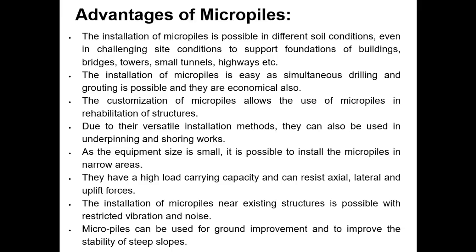The customization of micropiles allows their use in rehabilitation of structures. Due to their versatile installation methods, they can also be used in underpinning and shoring works. As the equipment size is small, it is possible to install the micropiles in narrow areas. They have a high load carrying capacity and can resist axial, lateral and uplift forces.